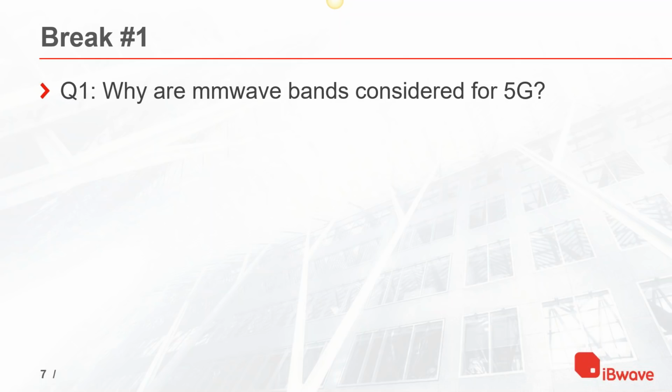The reason is that despite all that, those are very wide RF channels that those frequencies carry. Simply, the higher you go in frequency, the wider RF channel you're going to have. So at 24 gigahertz, and 24 to 39 to be precise, those channels are 850 megahertz. Because you have such a wide channel, you can carry a lot of information over that channel.